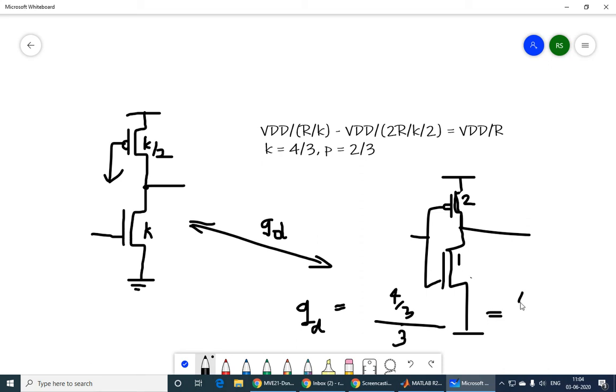Okay, so that is something that is relatively easy to calculate for all pseudo NMOS gates. When you're doing the calculation for GD, always your equivalent inverter is 2 and 1 because that is what we used to get in this equation. So by default, the equivalent inverter size is going to be 2 and 1 irrespective of the pull down network size.